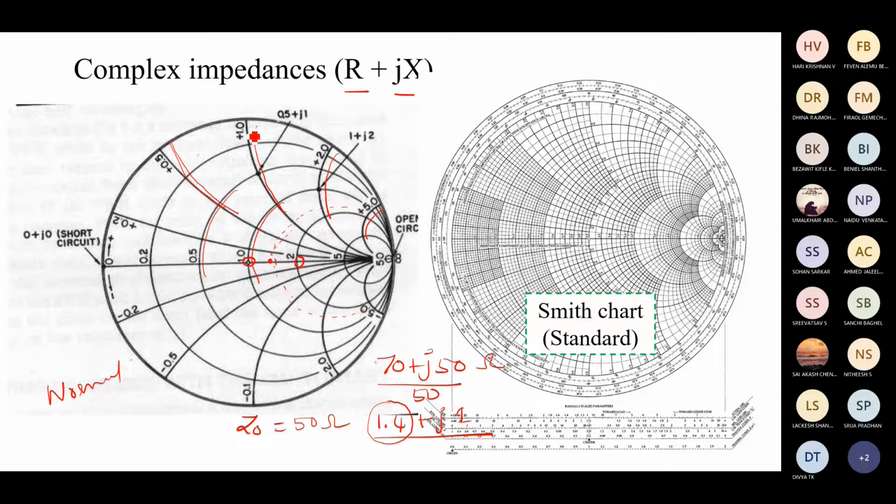You can see here, this is 0.5, this is 1. So this circle coincides with this particular point. So this is the impedance point. We always should represent this particular point as a small dot. It can be the small input impedance or small load impedance, whatever it is, we can define it in this way. And we can even move this point, we will see on the way.